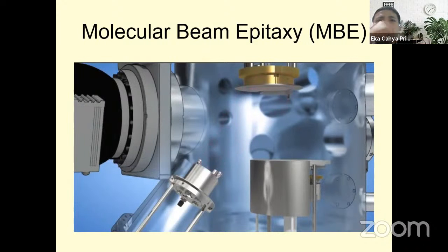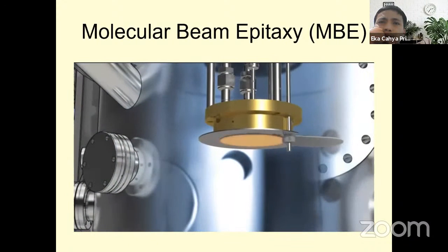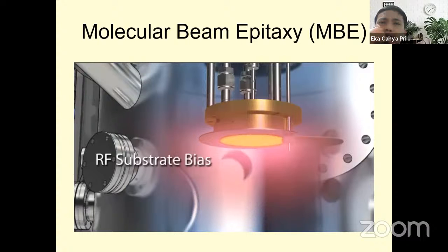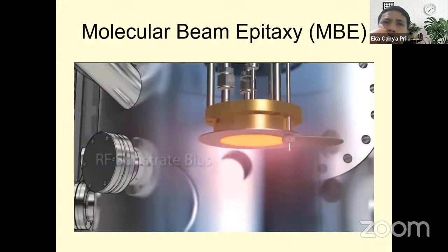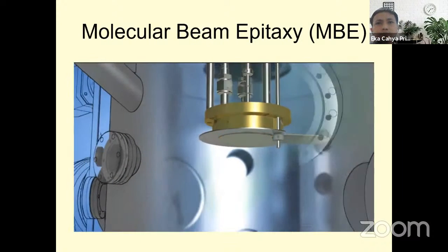The ion source can also be used for substrate pre-cleaning. Another option offered by PVD products is applying an RF bias to the substrate surface. This produces a plasma right in front of the wafer that can be used to pre-clean the substrate surface prior to deposition in a background of argon gas, or to conduct reactive film depositions of oxides or nitrides when sputtering or depositing films via PLD. This option does not occupy any of the ports on the back wall of the chamber, leaving them fully available for the other options noted, and thus can be integrated into almost any of our configurations.